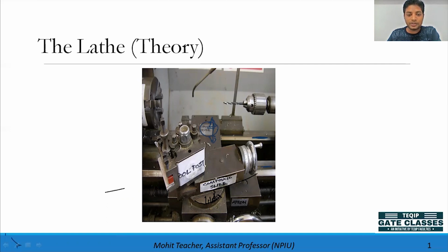This is in this direction, by the way it is horizontal, along the bed direction. If this were horizontal, it would be like this. Now over this disc there is the compound slide, and this compound slide is fixed over this, not fixed completely, but it can be movable.